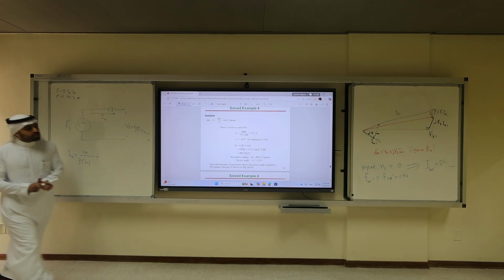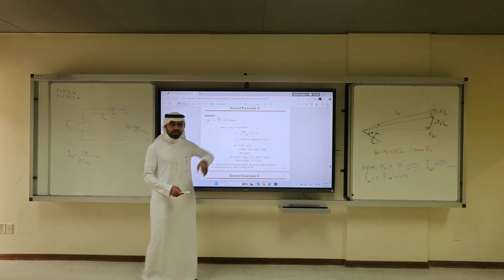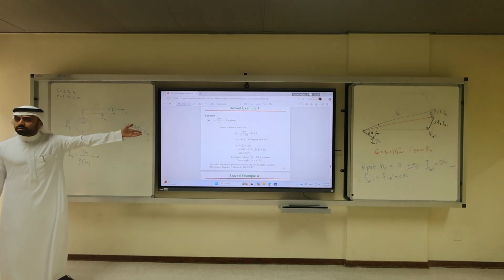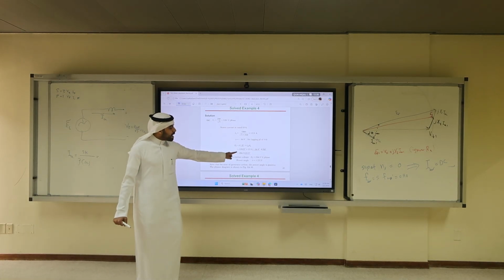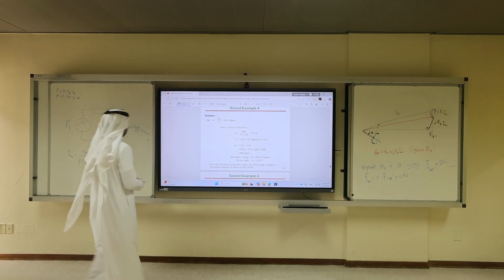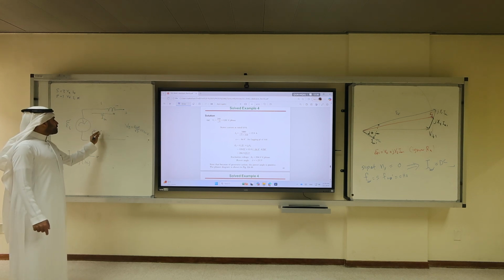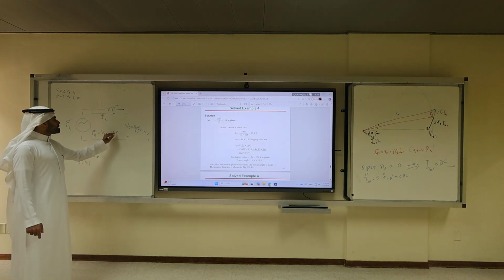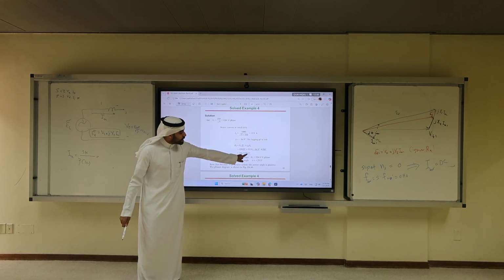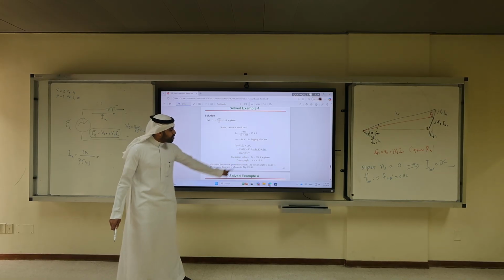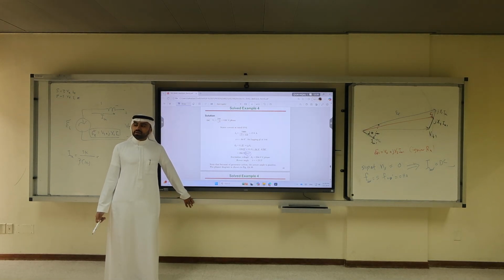Let's continue. Once you calculate the I, it's time to calculate the angle, and it's lagging, so the angle has to be negative. The angle is clearly negative inverse cosine of 0.8, which is 36.9. Add, do the KVL: EF equals the voltage rise, Vt plus j XS Ia. If you substitute, you get 206.9 at an angle of 25.5, and this is the torque angle, and it is positive. So it means we are at generator mode.